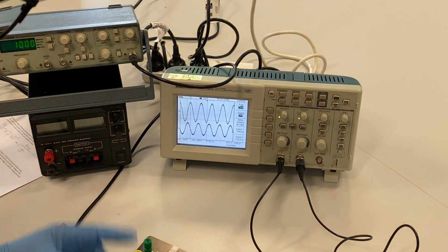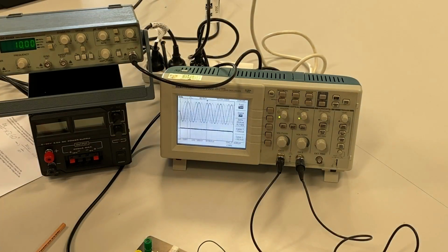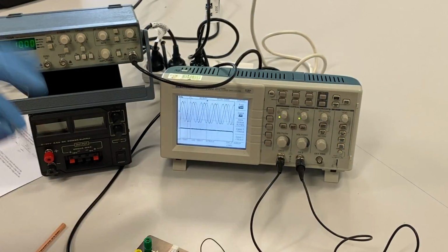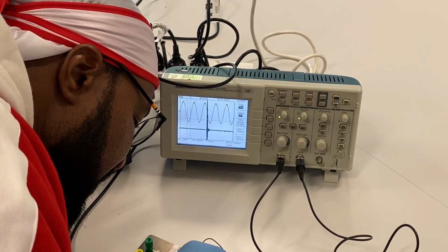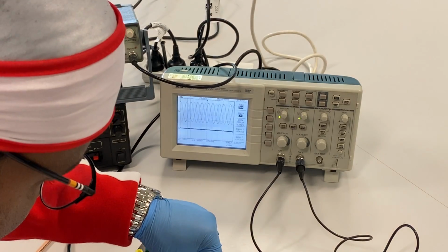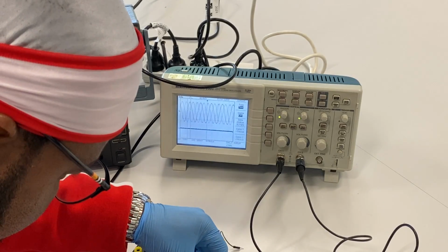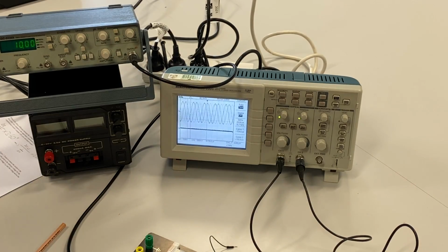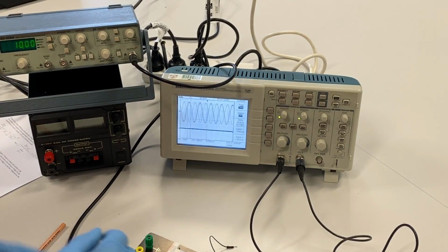We remove this resistor, so first we just disconnect the input voltage at this instant, right? Then I'll remove this 1K resistor. I'm gonna put a 0.1 microfarad capacitor at that point where the resistor was. There we go, right? Then I'm gonna put a 100 ohm resistor at the other end, which was initially the ground, right?